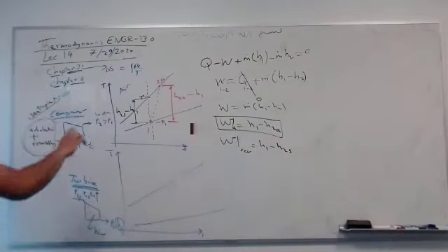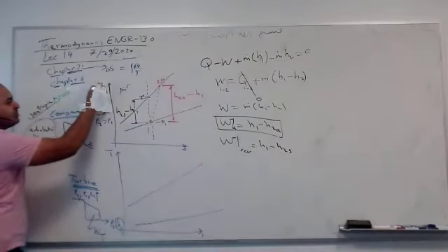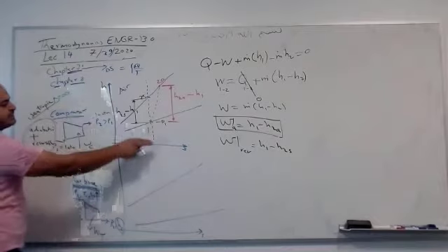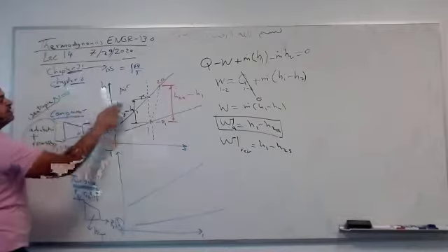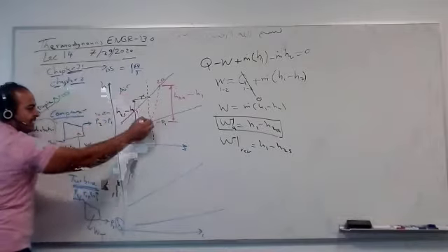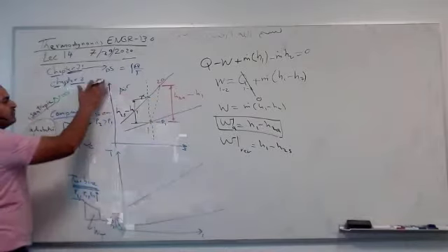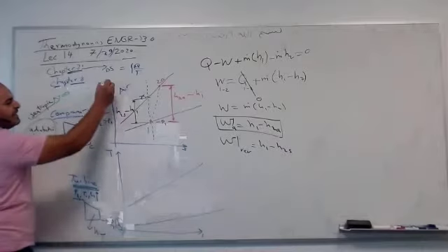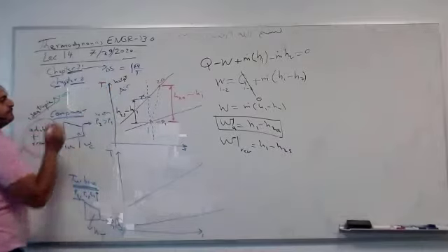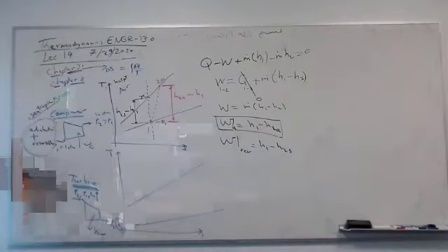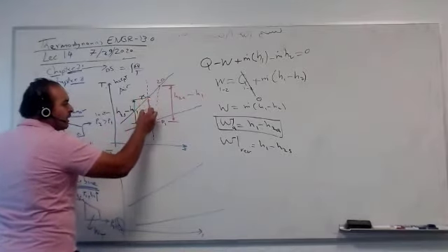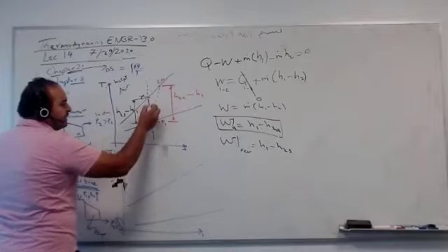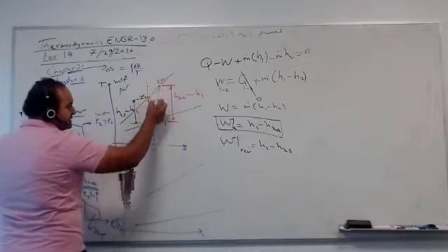So actually, this vertical distance, I can plot HS, US, PS, VS, TS, HS. The good news is that for air, H is just Cp times T, assuming that Cp is constant. So this vertical distance is related to the temperature very directly, or by integrating, the projection of this.